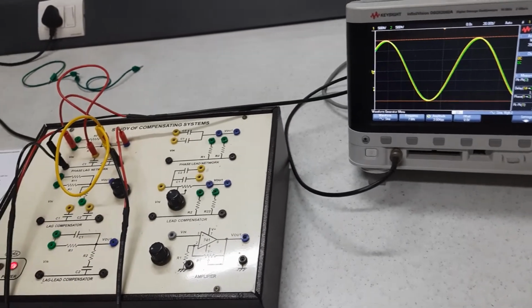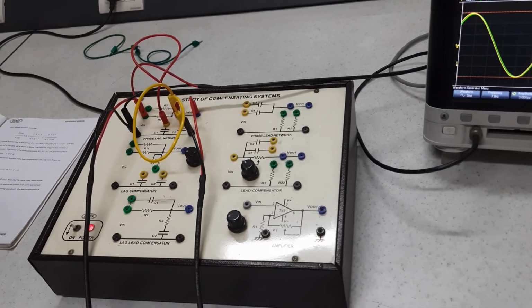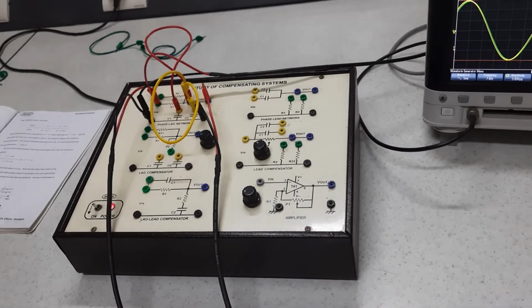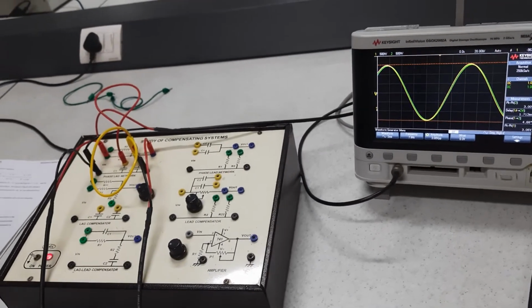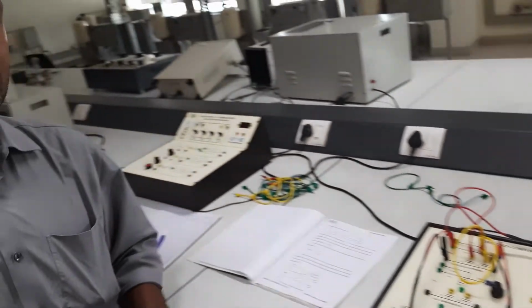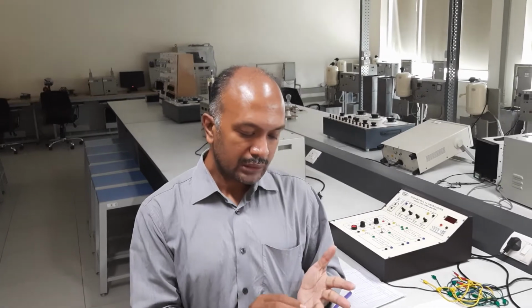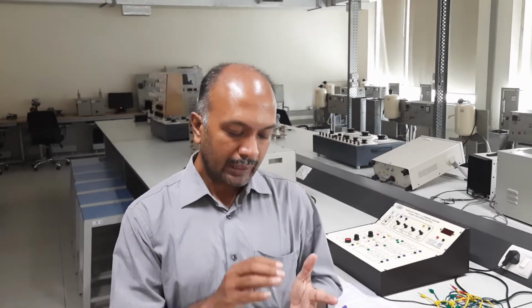Okay, now what is the procedure that you need to do is, you need to plot a Bode plot. The Bode plot is nothing but the response of amplitude with respect to frequency over a longer range, right? So Bode plots will give you a better picture. So you have to change a very large range of frequencies, and tabulate what is your input frequency that you are giving, what is the input voltage that you are giving, and what is the output voltage that you are getting.